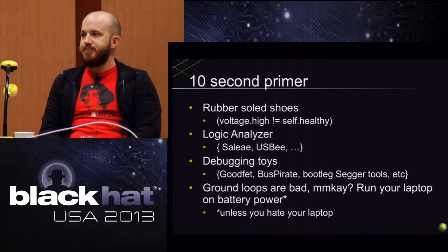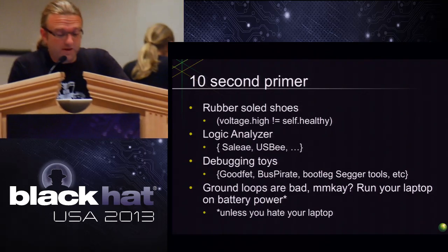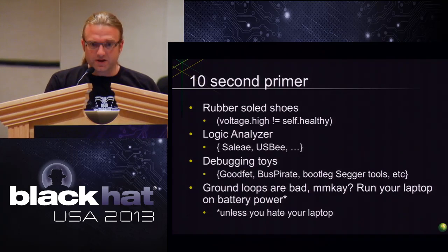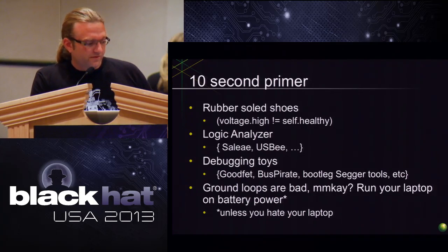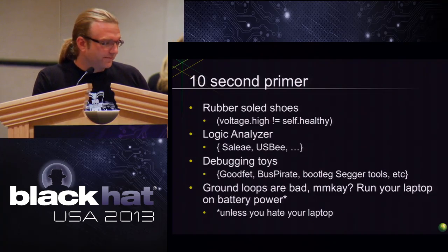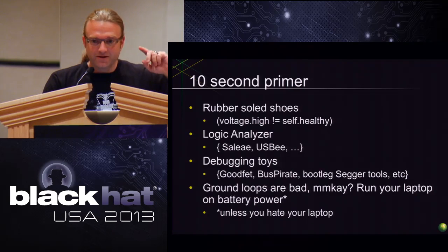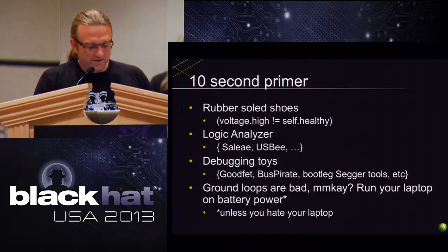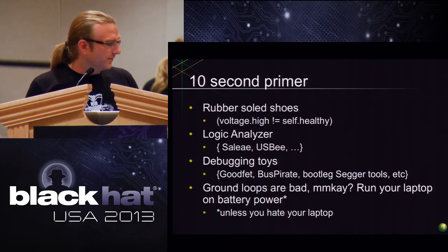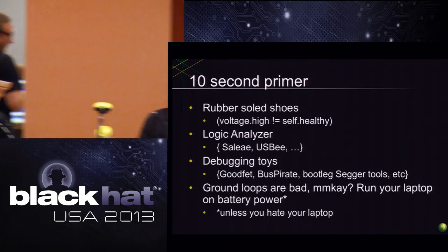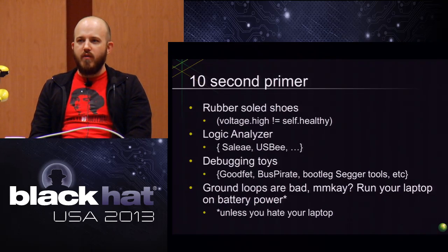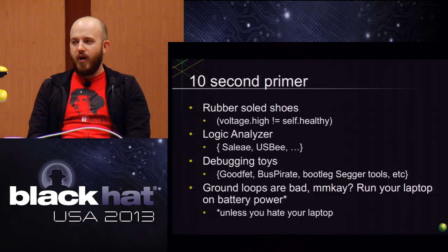Yeah. And the last pro tip that we've got before we really get into the meat is if you're working on high voltage or typically almost any embedded system, if you are powering that device and you're running ground on the same plane that you're running your device, like if we're running 110, your laptop doesn't like that and you end up doing things like frying your USB ports. If PCBs were designed correctly, that would never be a problem. But when you get into debugging interfaces and stuff like that, there's a couple of them out there that are known for letting you electrocute yourself or frying your laptop. Yeah.